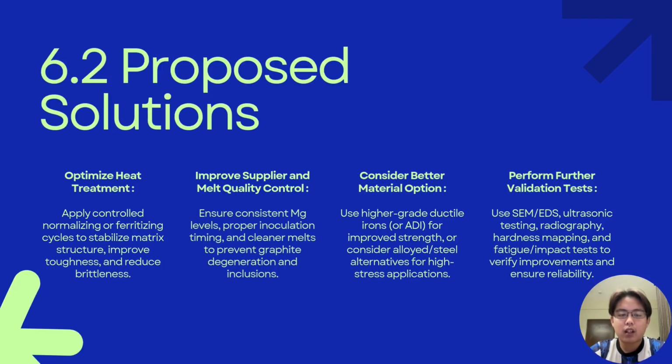Finally, we recommend conducting further validation tests such as SEM and EDS analysis, ultrasonic testing, radiography, fatigue testing, and hardness mapping. These tests will help verify that the improvements are effective and that the material meets performance requirements. With these solutions, the overall reliability, strength, and ductility of the component can be greatly improved.